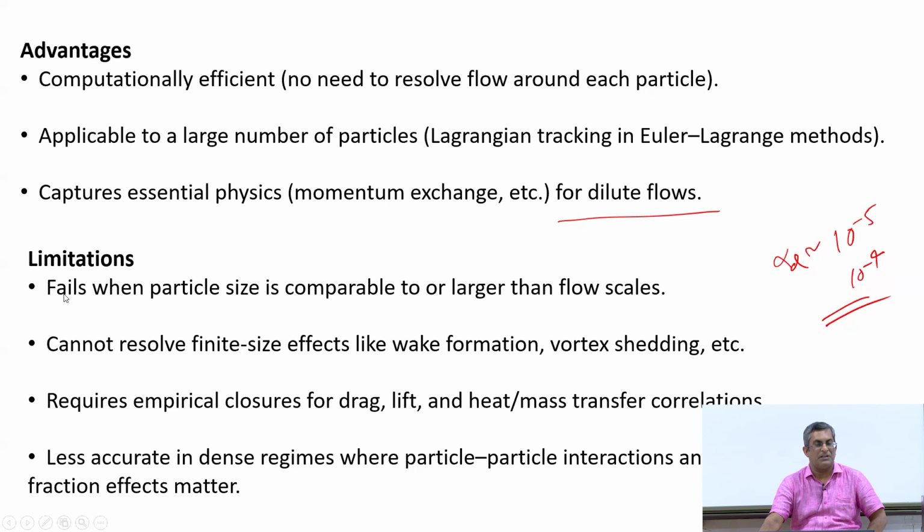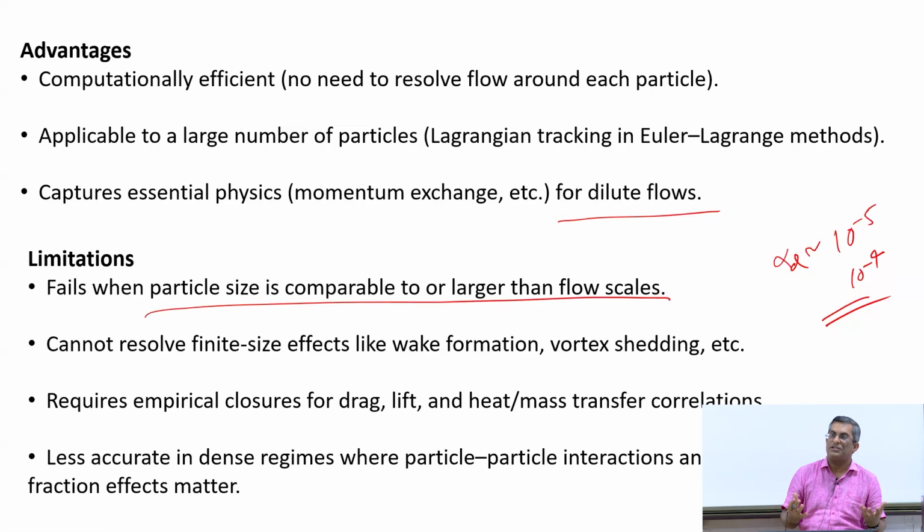First of all, it will fail if the particle size is comparable to or larger than the flow scales. It will not work in that region. The main problem here is that you can still do a simulation, even if the particle size is large, but it won't give you any physically correct result.